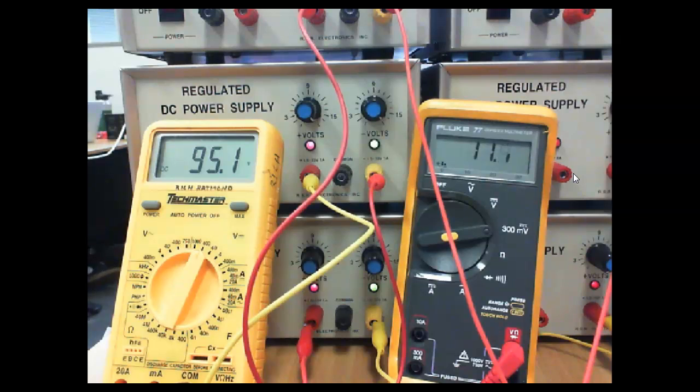So why aren't we damaging it? Well, we're watching the voltage, we're watching the current really well, and we're protecting this with a 1 mega ohm resistor. And you don't see many 1 mega ohm resistors. We used to do it with a 10, but it gave us a little problem because it gave us invalid voltage measurements. And the problem people don't understand is that when you put a meter in parallel, it acts like a resistor in parallel when you're measuring voltage.